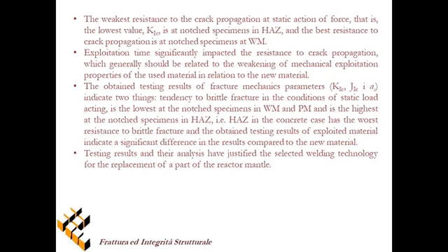It can be seen that exploitation time significantly affected the resistance to crack propagation, which generally should be related to the weakening of mechanical exploitation properties compared to the new material. In addition, testing results and their analysis have justified the selected repair welding technology used for the replacement of a part of the reactor mantle.